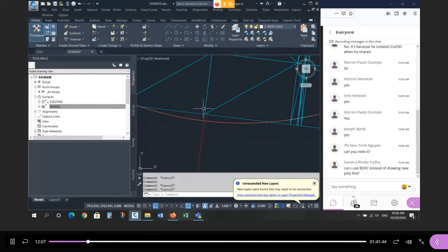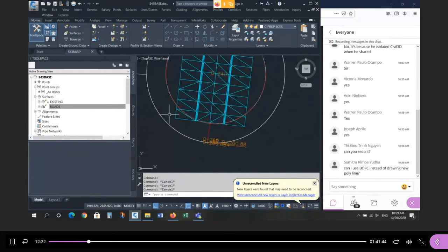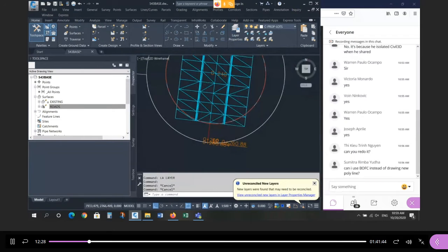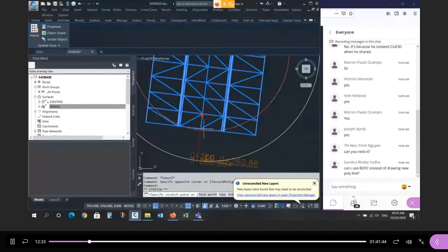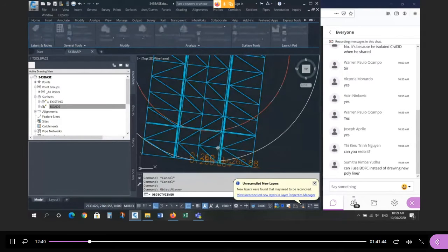Remember, we made it shorter so that it ended at the edge of asphalt. Okay, so there's a couple of things to be mindful of. I'm going to take this, not this, but the corridor model. So let me bring the corridor model back because I have to revise the corridor to change the surface. So the corridor model is now here. There's the grip for it. So I'm going to make it go all the way to the end, and it's going to create a spike, which is fine. Okay, so if I look at this surface, it's going to have a spike at the end.